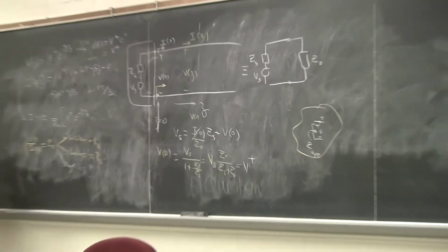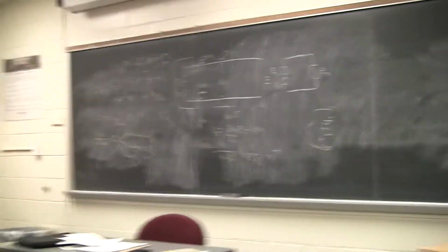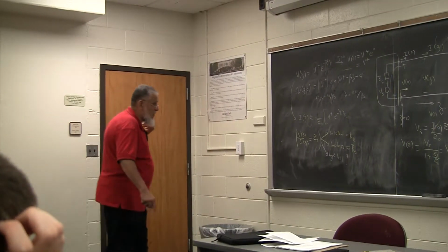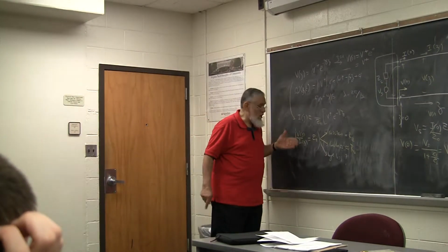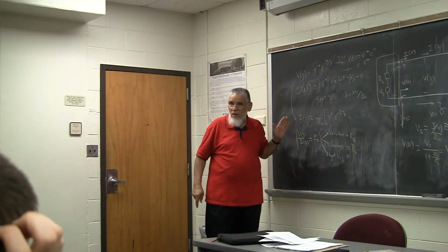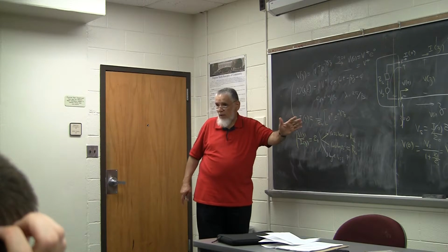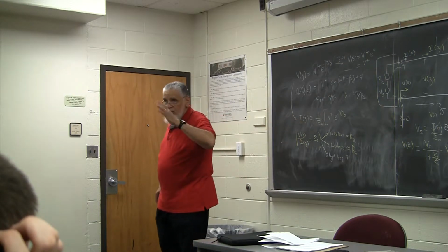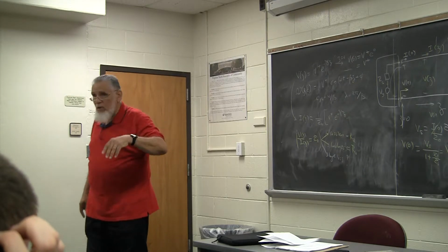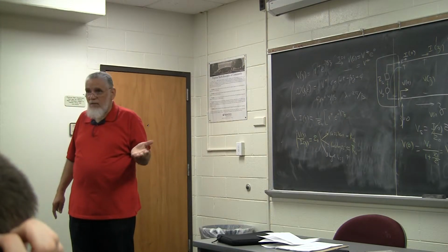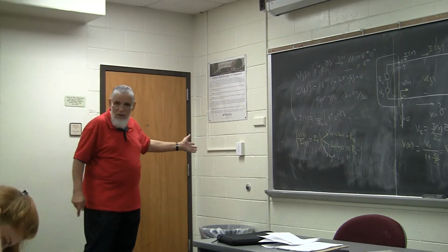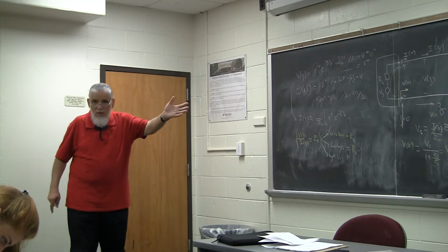The simple case of one source of traffic one way, no signals in the other direction, no waves in the other direction, gives you a uniform and constant impedance throughout the whole line. So sometimes we define the Z0 as the input impedance of an infinite line. Because that infinite line is the one that we're discussing right now. The line that doesn't have any reflections.